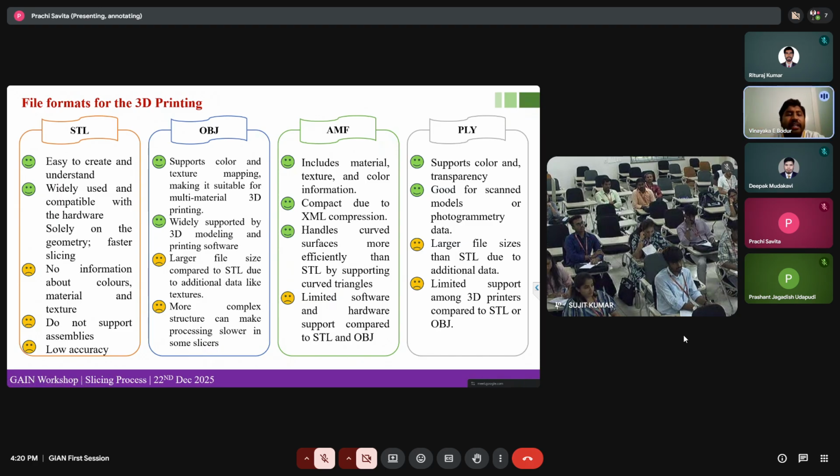The structural integrity of an STL mesh depends on the vertex rule, which dictates that every triangle must share exactly two vertices with its neighboring triangles. This ensures that the mesh remains a closed manifold, a closed manifold polyhedron, a condition often described in the industry as being watertight, meaning it is completely tight inside.